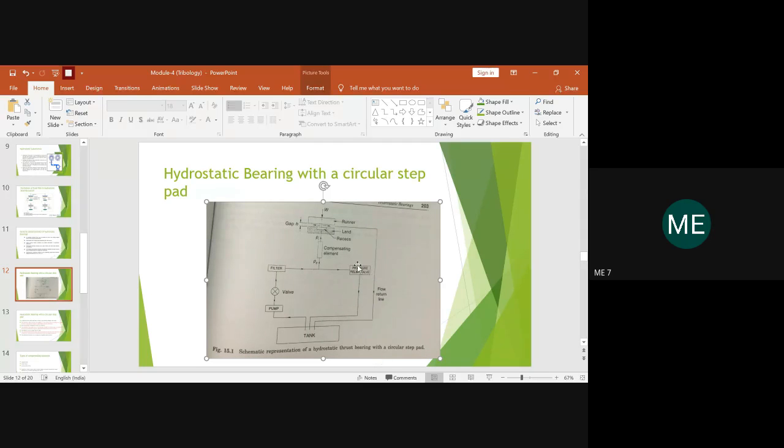So this pressure relief valve will relieve the pressure associated with the oil which is passing through it. So once the entire pressure of the oil has been relieved, the valve here opens. So the normal oil or the lubricant will pass through with zero pressure or negligible one, and it comes back to the tank. It will be in the reservoir until the next use when needed, it will be used.